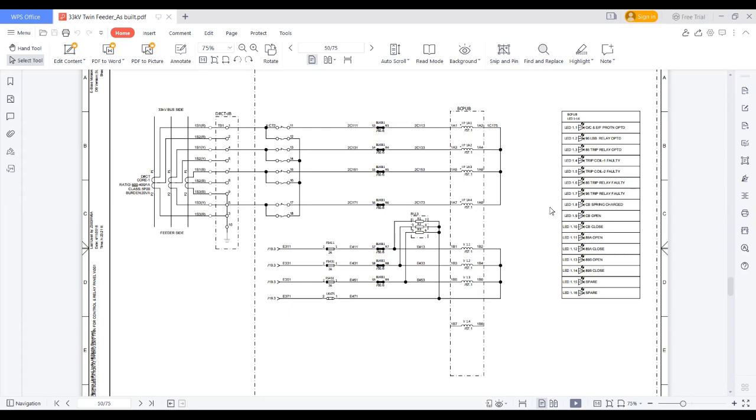Third, the AC circuit and the DC circuits. In the DC circuits, whether he provided the DC connections for all the coils and the relays or not. And fifth, the PT distribution circuit. In the PT distribution circuit, whether he did the wiring exactly as we provided in the PT drawing or not. So we are providing the PT drawing and distribution board drawings.